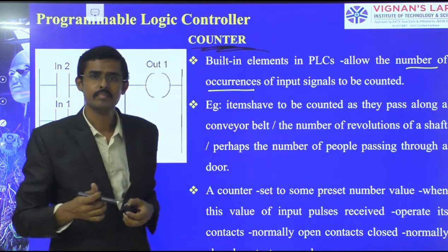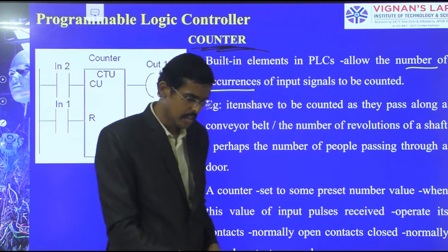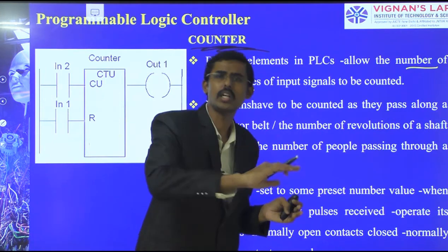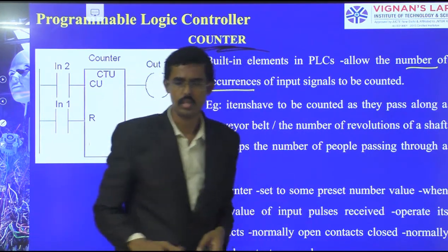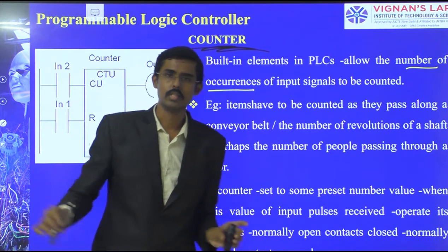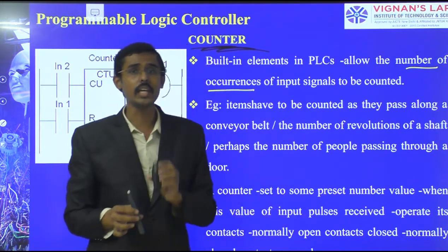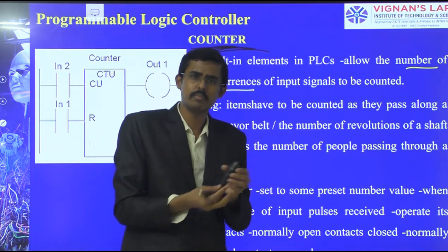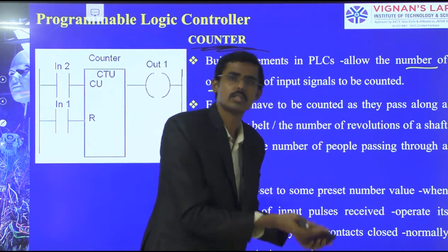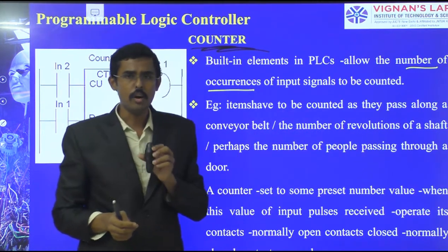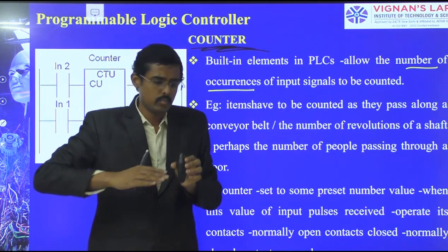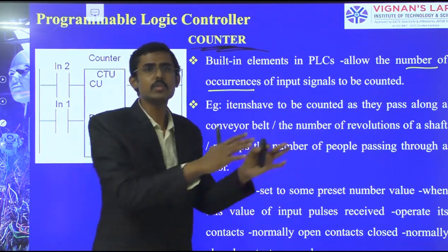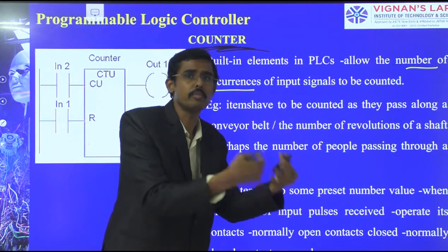Let us consider, I want to fill a biscuit box on the trolley with 20 objects, or 20 biscuit packets in the box. One object detected, stored. Second object detected, stored. Until 20 counts, the trolley should move, and therefore the biscuit can fall in the filling box. So after 20 counts, the trolley should stop. The object should not fall in the filling box. Therefore, each box may contain 20 counts of biscuit packets.